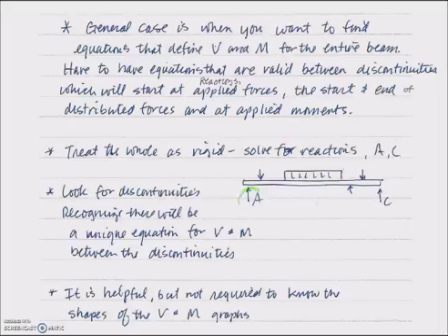So where this reaction is, is the beginning of a discontinuity, but here we have an applied force and the beginning of a distributed load. Right here, that's going to be a discontinuity, and then another one. And then we'll have another applied load, and another reaction. So every place where there is a change in the application of a force, there will be a discontinuity, and we'll talk about those as we go along.